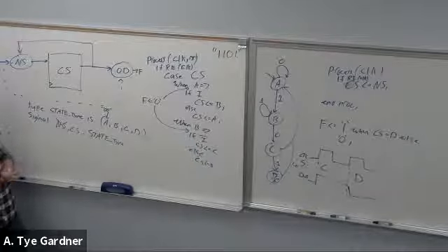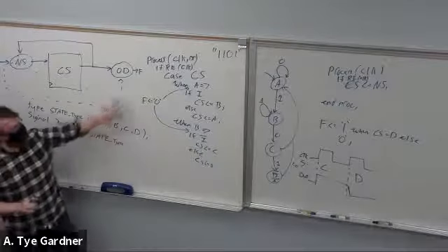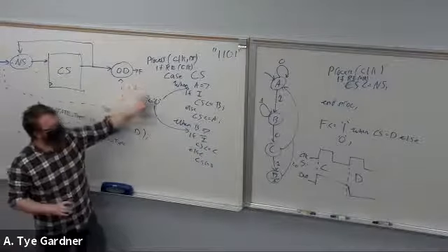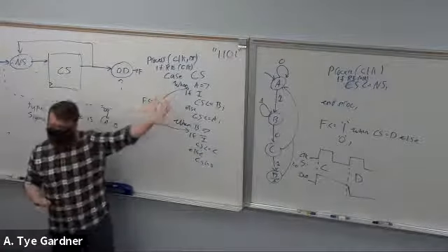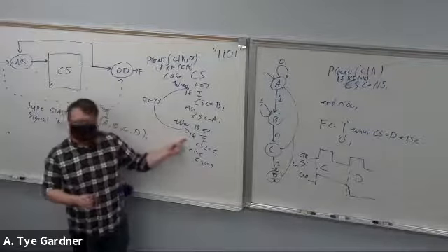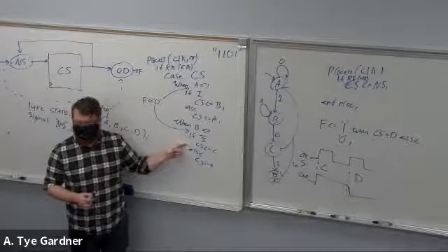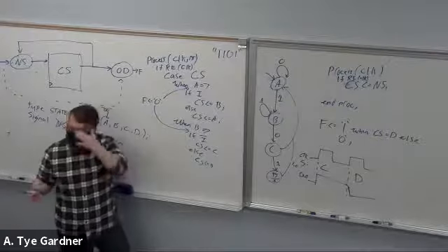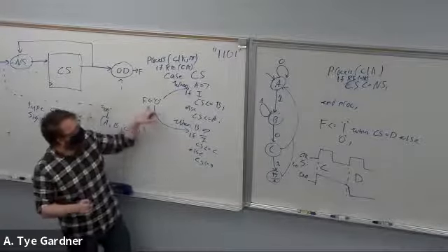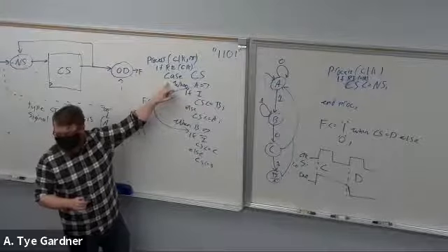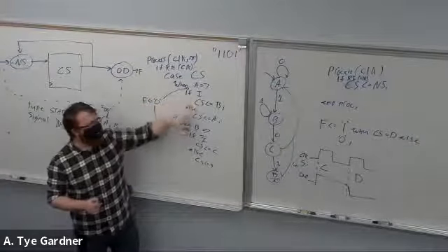I will actually get to that because that's a good question. Literally what I was coming up to next. So here works if you're outside of the if statement. If you're putting them in the if statement, you would do this sometimes because that's how you change it from a Moore state machine to a Mealy, right? Because if it's in the if statement, now the output depends on the input, not just the current state. So what you're suggesting turns it into a Mealy machine. And so it's something you might actually do. If you were to do that, instead of putting any outside of the if, you would put all of your outputs inside both the if and the else.